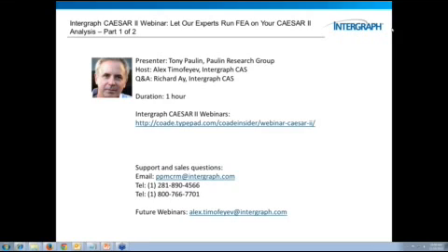There was one more question that has come up. We talk about ASME codes allowing the use of more applicable data, and in the EN piping code there is also a similar statement. But Tony, have you seen if other codes allow similar methodology to be used, to use SIFs based on FEA?